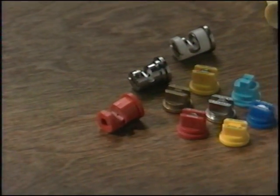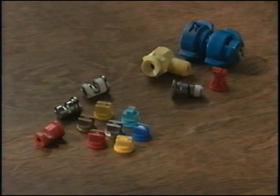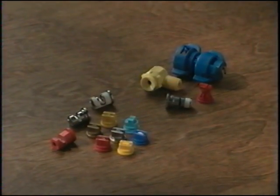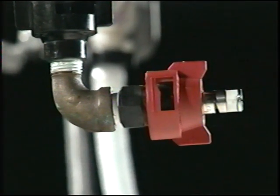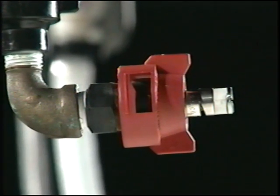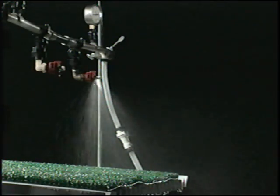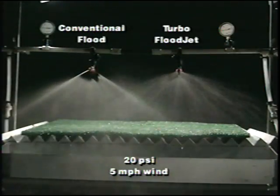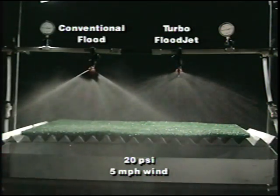Aside from the wide variety of traditional extended range flat fan and flood spray nozzles, there is a new generation of nozzles designed specifically to reduce drift. For example, let's look at the turbo flood jet nozzle, seen here at 20 psi pressure and a 5-mile-per-hour wind. With its pre-orifice turbulation chamber design, this new nozzle produces larger, more consistent droplets in a uniform pattern by directing the spray downward instead of on an angle, usually 45 degrees to the rear. Comparing the turbo flood jet side by side with a conventional flood nozzle, note the significant improvement in drift resistance.